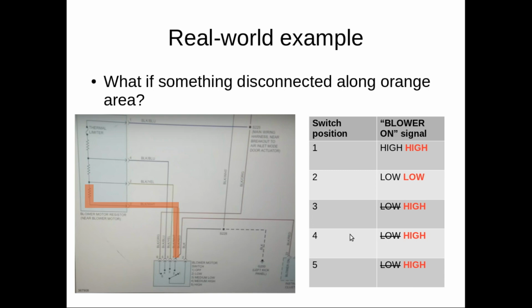So this looks like a very plausible potential fault. Something got disconnected here. What we'll now need to do is to go and check this resistor and this wiring, and maybe that will turn out to be exactly our issue, and that would complete the diagnosis. So in this situation, the truth table again provides a direction for further diagnosis.